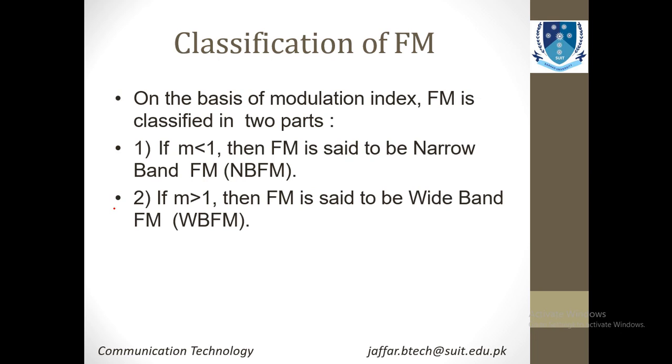I repeat again, if your index is less than 1, let's say 0.6, 0.7, 0.8, 0.9, or even 0.99, if it is less than 1, you term this FM as NBFM. And if the index of your modulation is greater than 1, this FM is considered to be wideband FM.